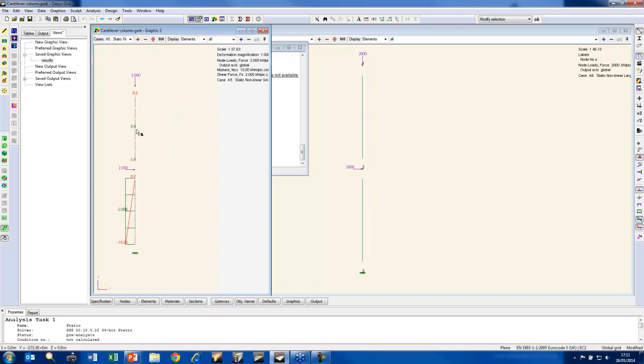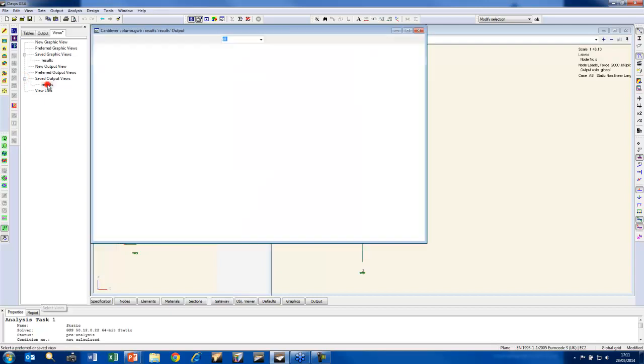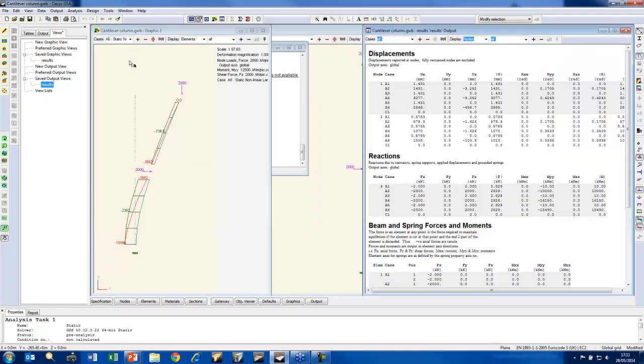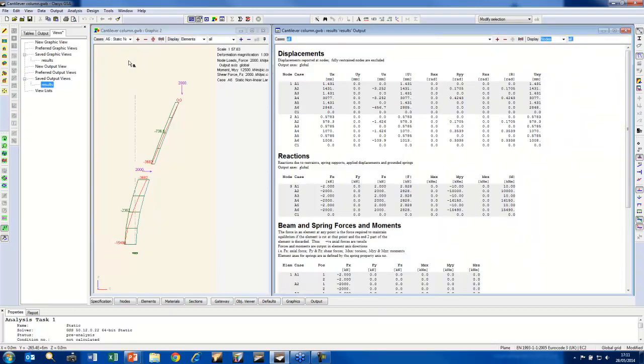Non-linear analysis, again, is exactly the same as the linear for the smaller load, but with the non-linear we are getting much larger moments, including at the top part. Now you might be asking, what is the difference then between the P delta and the non-linear? Well, let's quickly look at the individual cases. So A1, A3, and A5.